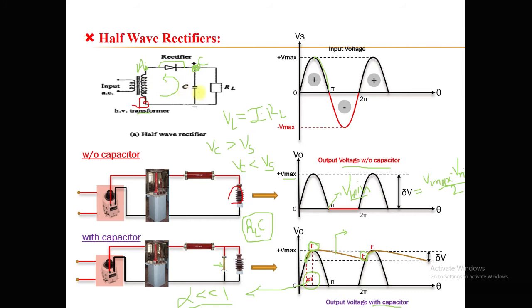One duty is it refills the charge which is lost by this capacitor to drive the external load circuit, and second, the current supplied by this transformer secondary to the load side. But generally we are eliminating the component of the current which is driven to the load circuit because of this lesser value of alpha. So whatever the energy has been supplied by this transformer is entirely available for charging of the capacitors only.